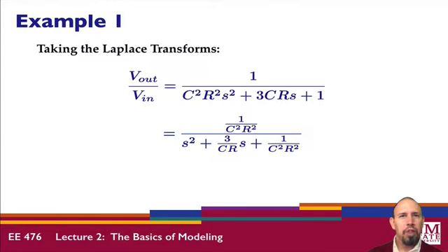So using all the circuit equation knowledge that we have obtained from various previous classes, we can create a model for a circuit, just like this circuit we did here. Now, notice we've only used passive components, R, L's, and C's. We could have used M's, that is the memristor. But we didn't use transistors, we didn't use diodes, which are nonlinear, which have a nonlinear characteristic. Okay, so at this stage, we're keeping everything essentially linear. Not totally linear, but essentially linear.